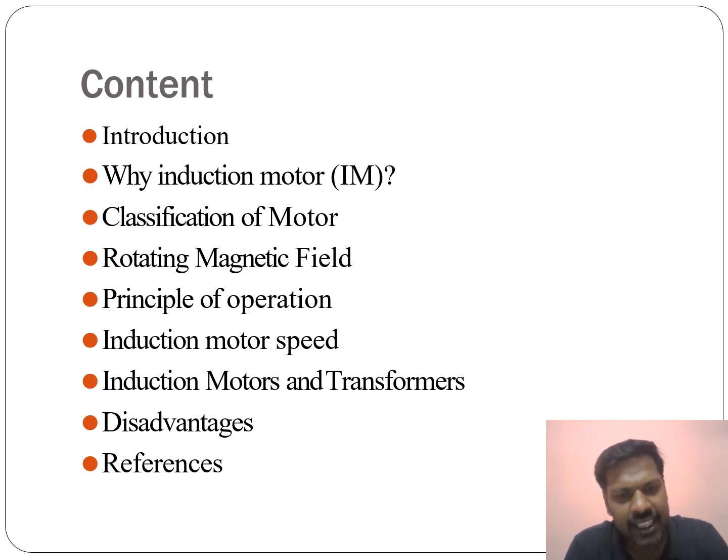The speed of an induction motor depends mainly on the frequency of the power source, which means its speed is essentially tied to the supply frequency. Because of this dependence, varying the speed is not straightforward with a fixed frequency supply. For good variable speed control, induction motors require a variable frequency power electronic drive.